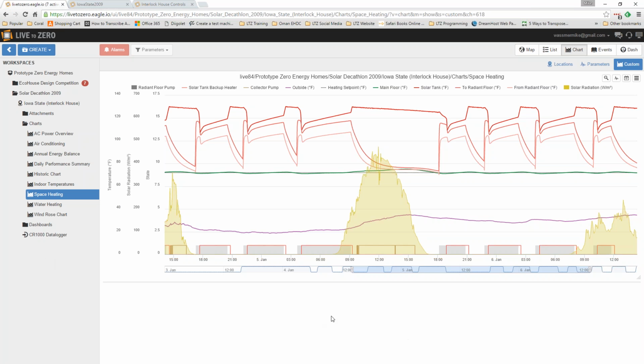and that's why when you design a heating or a cooling system for a building, it's very important that you don't oversize the system. And undersizing it means you may have comfort problems. Oversizing means that the system may fail earlier, it won't be as efficient, and so it's the cost, also less comfortable because it's turning on and off more. So now this building doesn't have as much issues during heating season with comfort because radiant floor heating is very comfortable. It's comfortable from an acoustic standpoint because you don't hear it coming on and off. And you also don't feel the temperature fluctuations as much.